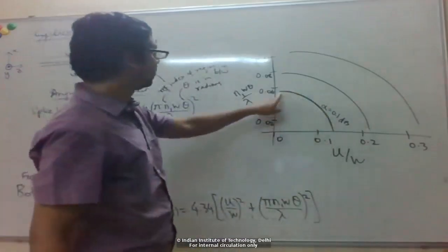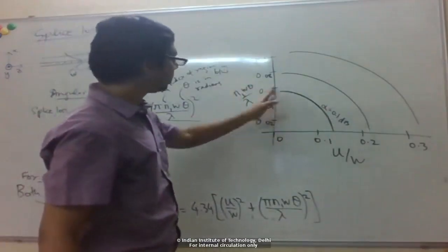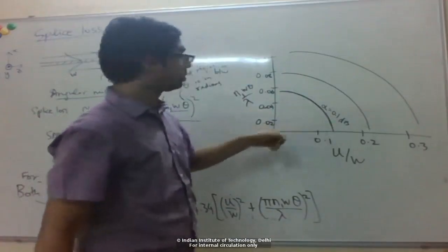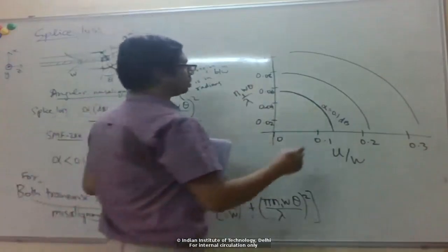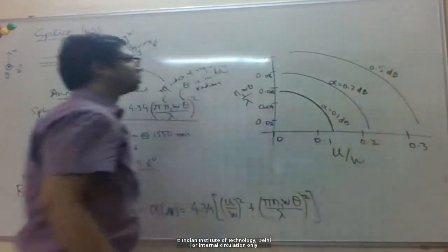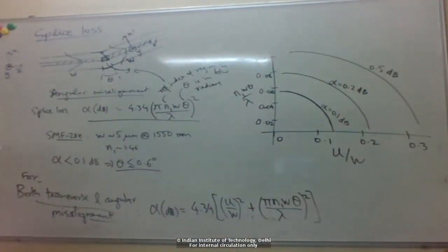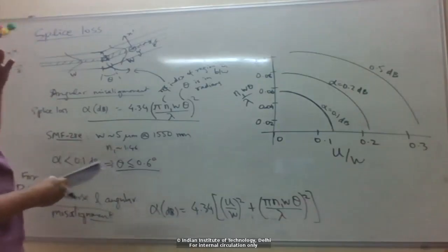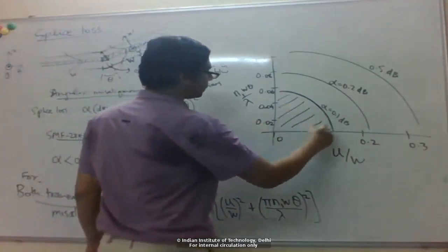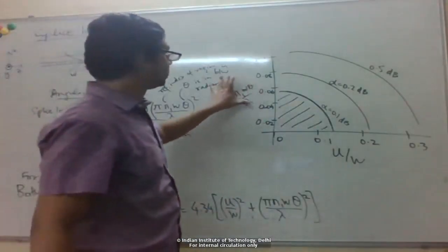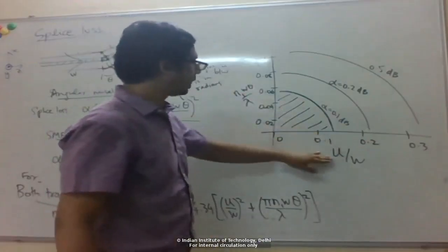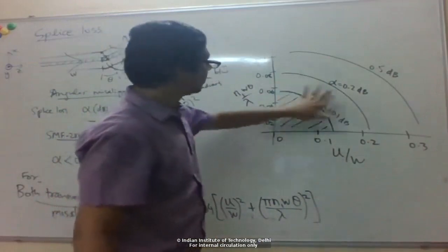You can see either I could have high angular misalignment but very low transverse misalignment, or I could have relatively high transverse misalignment but low angular misalignment, because there's a trade-off. And this is for 0.2 dB, this is for 0.5 dB. Again, for the specs we want to achieve, we want to lie in this range. So the angular tolerance and the transverse alignment tolerance of the splicer I'm using had better be in this range. If it's more than that, then I have high loss.